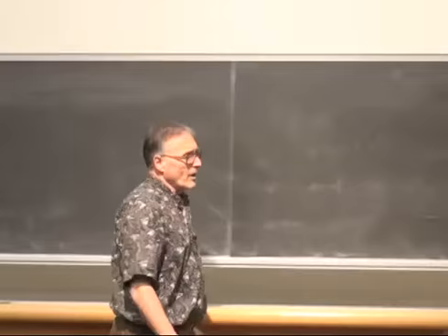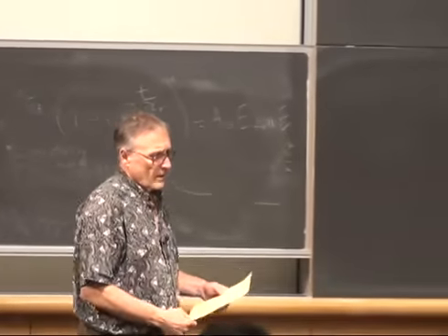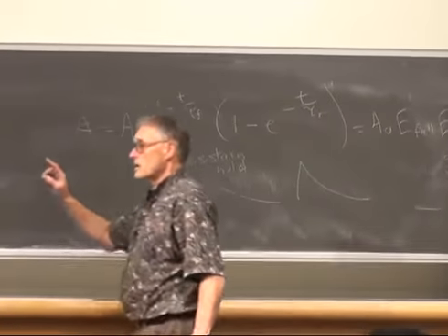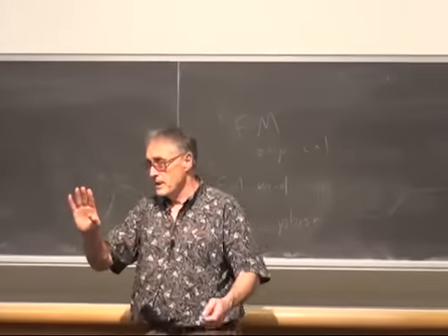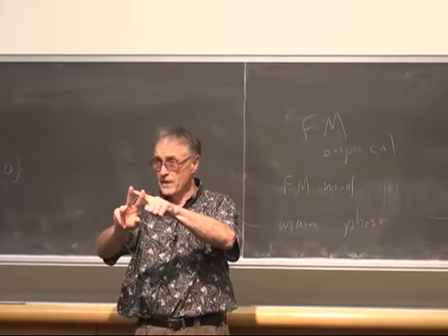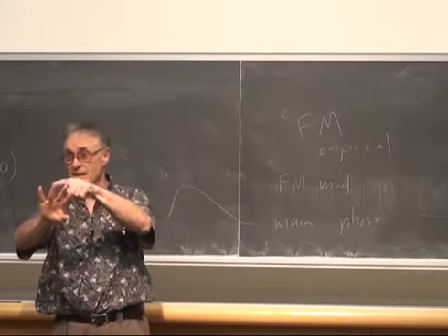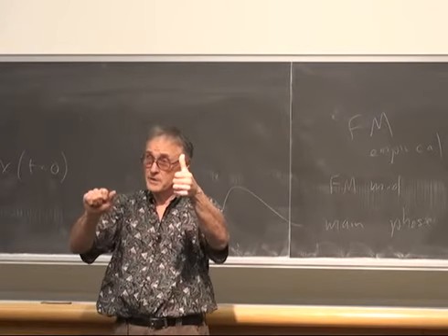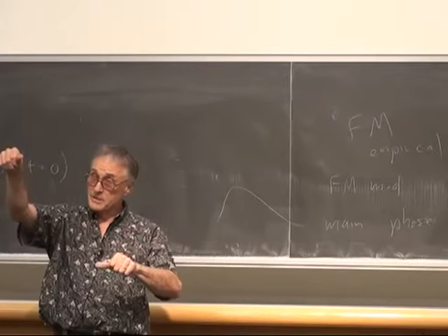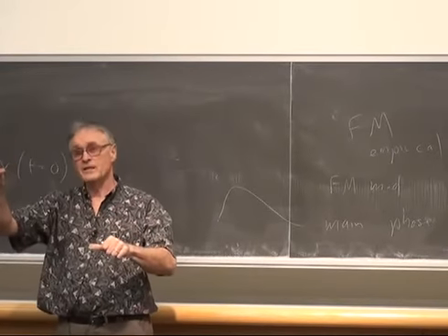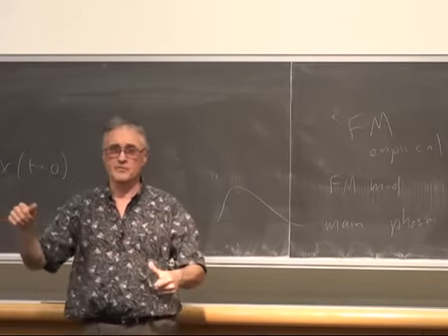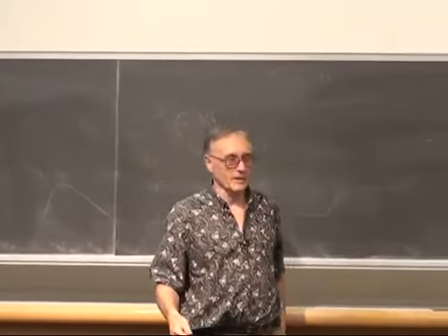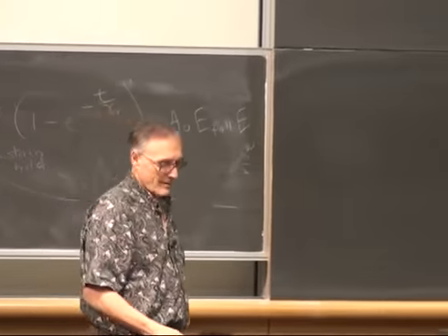And to see how well this worked out on PIC 32, I implemented an FM system. But now the FM system has attack and decay for the FM modulation. It has attack and decay for the main sine wave. It has 2 phase accumulators, one for the main frequency, one for the FM frequency. And the whole thing takes only 5% of the CPU using 32-bit fixed point. So you can build a lot of these things if you want to make an interesting sound.